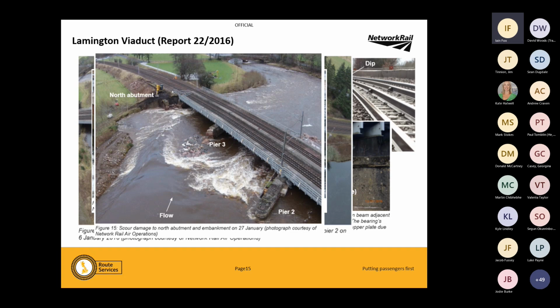The maintenance team waited till the next train, the 840, passed at track speed, and they observed very large movements in the track, and they then shut the line so they could figure out what was going on. And it was determined that a pier had collapsed underneath by train movement vibration. It was pier 2 that collapsed. Obviously, we've got a missing block, a few vertical cracks, some fractures, all sorts of things. We've got a displaced bearing plate. Lots of things wrong with pier 2. Okay, so that's pier 2, cunningly labelled pier 2.